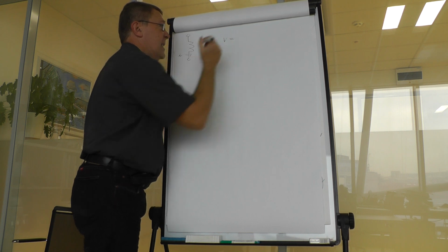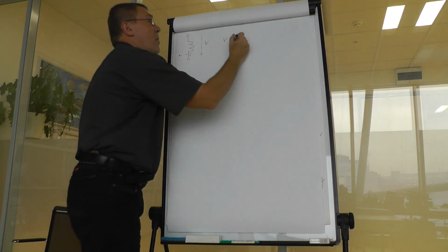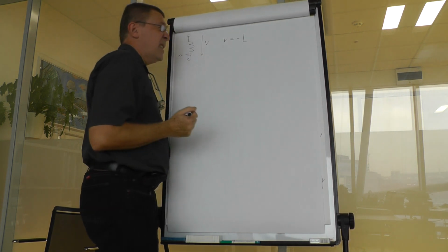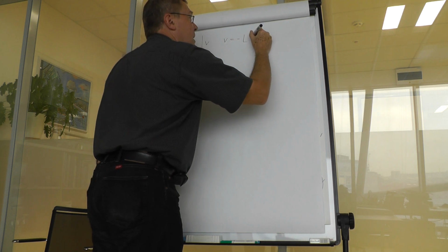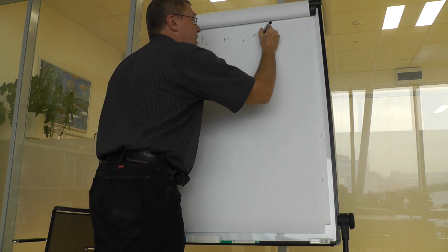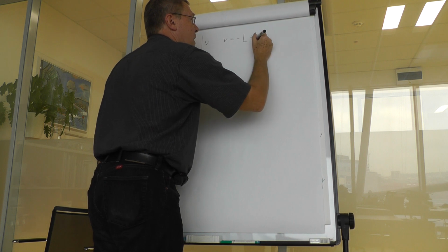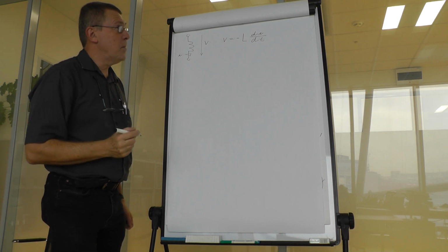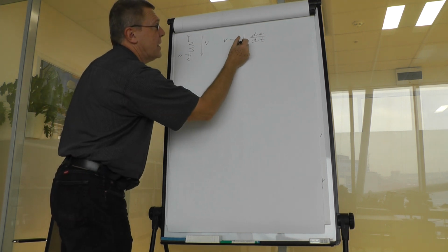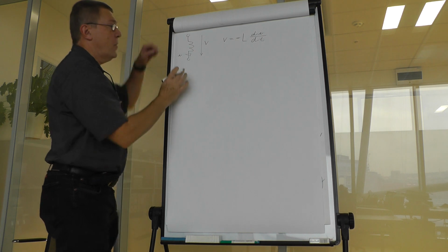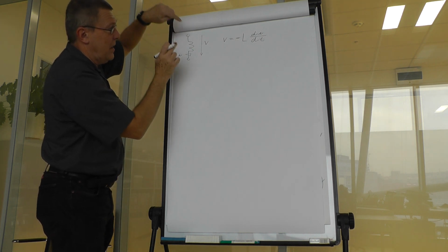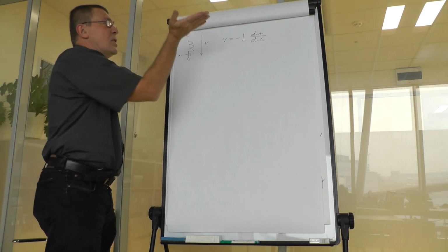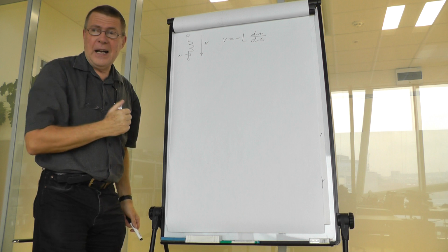voltage is minus inductance times time derivative of current, that is di over dt. Please note minus. So the voltage and current in this picture have opposite directions. That's the circuit theory definition of an inductance.